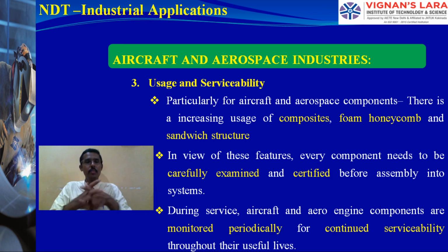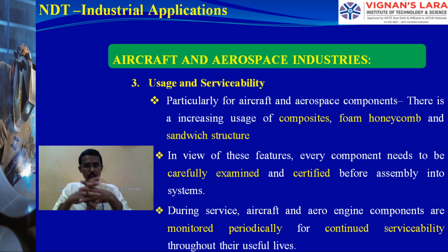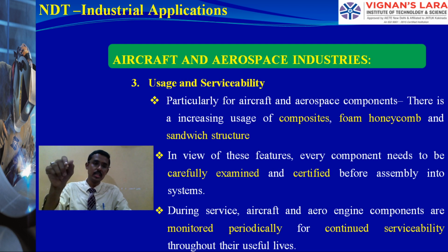Otherwise, the material's properties will differ. BCC to FCC will form, and definitely the magnetization property will change. Those things are all there, for example. So each and every material we use has to be kept in mind, along with its serviceability, usage, working conditions, and load factors. Accordingly, we should plan for these influences, and accordingly we should plan the NDT techniques to be applied there.